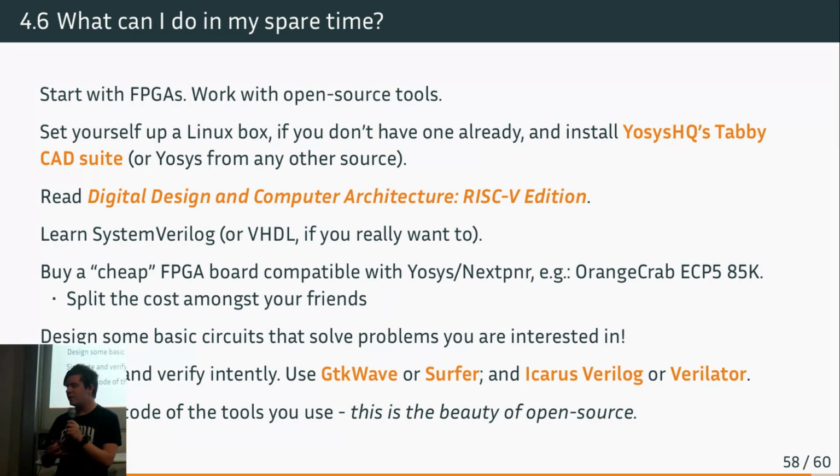So what can you do in your spare time? I think you should start with FPGAs and work with open source tools. This is where me and professors will differ, because usually professors want you to use Xilinx and proprietary tools. I started with open source tools because I didn't have access to proprietary tools, and that's how I learned. If you don't already have a Linux box, set yourself one up, and you can install Yosys. They have the Tabby CAD suite, which you can install very quickly, or you can also get Yosys from any other source you want.